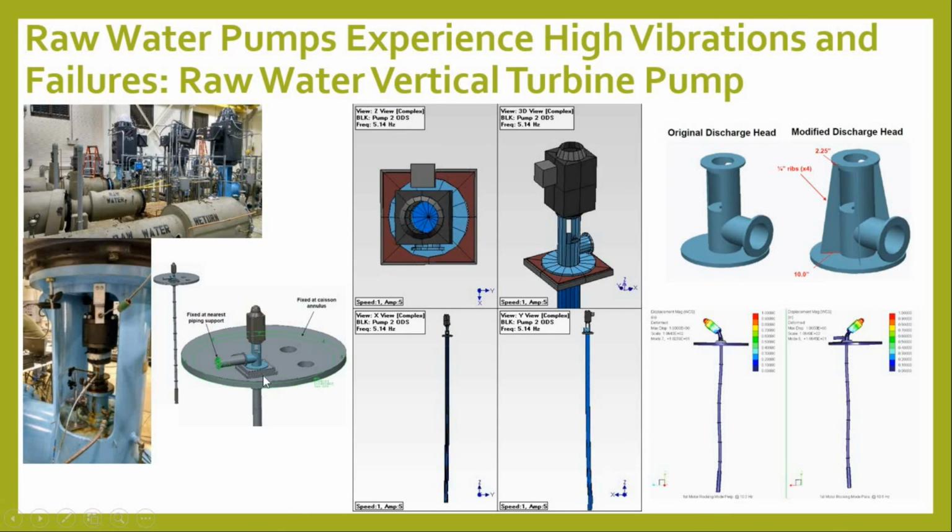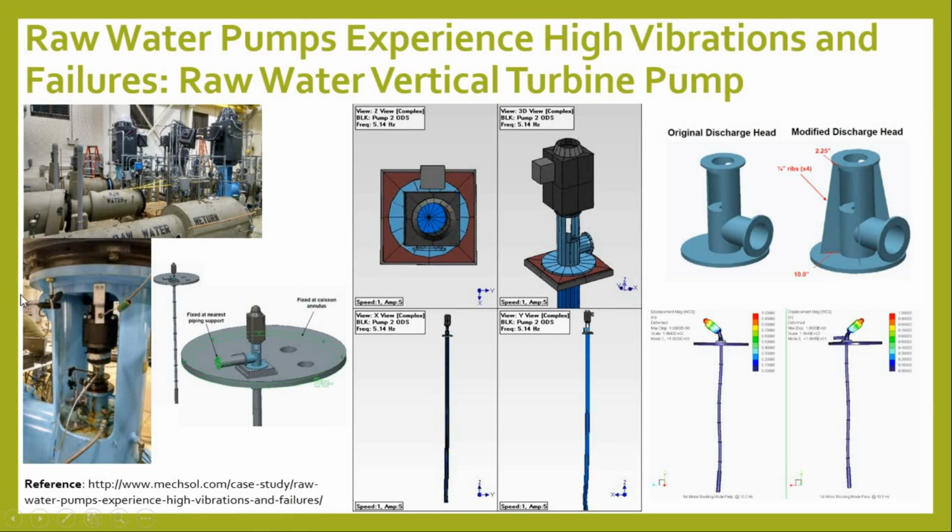So like that, when you come across vibration simulation problems where the problem is coinciding with the natural frequency, in that case you need to put in some additional ribs, or you can strengthen that model, so that we can shift that frequency away from the natural frequency, right? So we will reduce the chances of resonance in those cases. This is one of the case studies I referred from this reference. You can go through this reference for more detail.